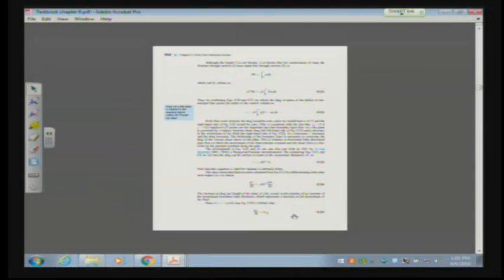All right, so then figure 9.11, we have another control volume. There. We have another control volume problem where we take a look at a streamline and a boundary layer edge with that velocity profile again. So one of the things I'd like you to see is that we keep seeing the same sort of variables and factors every single time. All right, now there's a statement that tells us that the drag on a flat plate is related to the momentum deficit within the boundary layer, which also makes sense, but this equation, 9.22, actually expresses that mathematically.